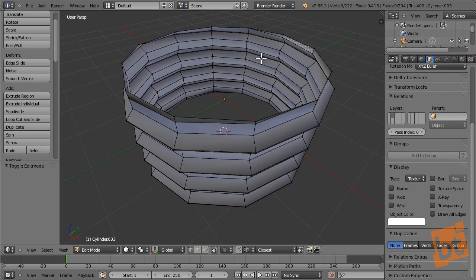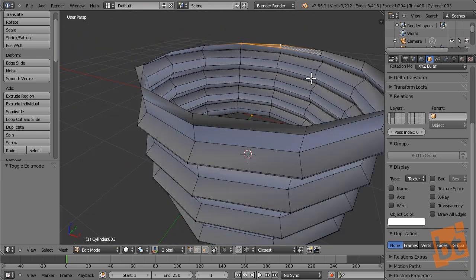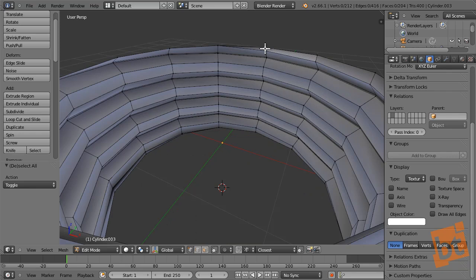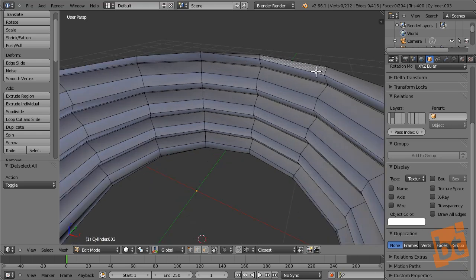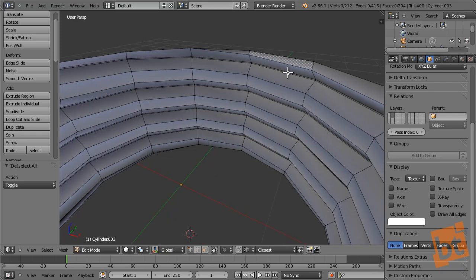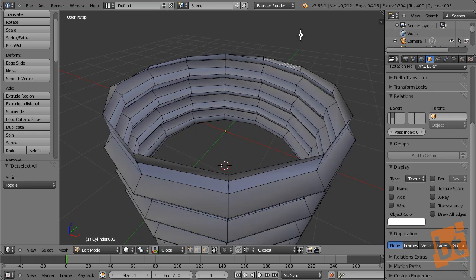Now we need to join this to the nut to keep going. All right. If you are worried about those triangles, we will try to clean them later. But before playing with the geometry in the borders, I want to join it with the nut, so then we can see the effect of that geometry. Sometimes I play here with the geometry to make it all quads, and then when I weld this to the vertices in the nut, it doesn't look really good. So I prefer to join this with the nut first.